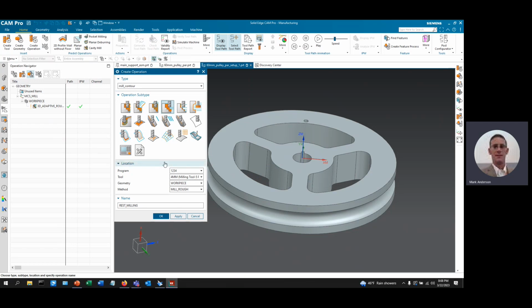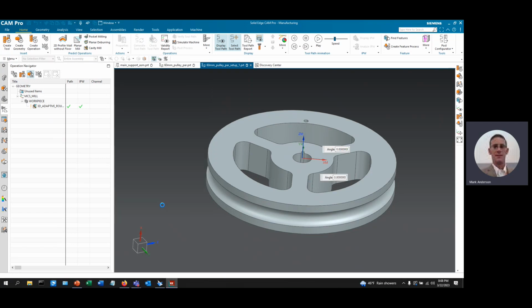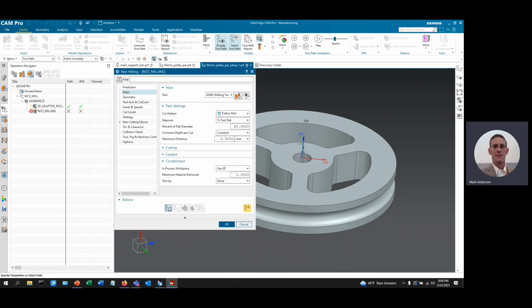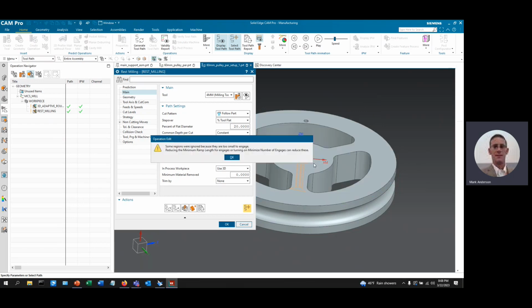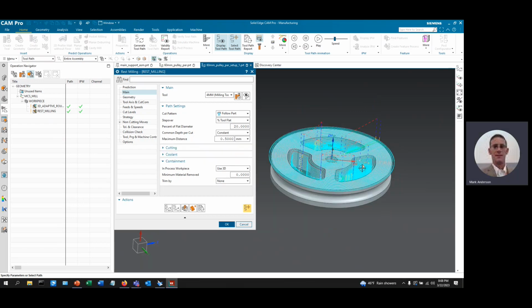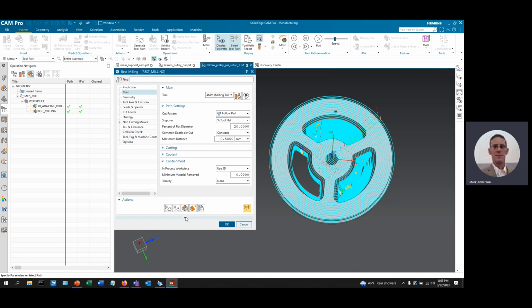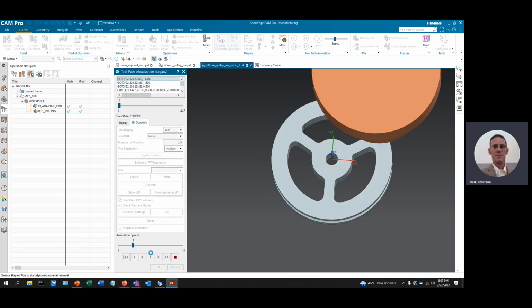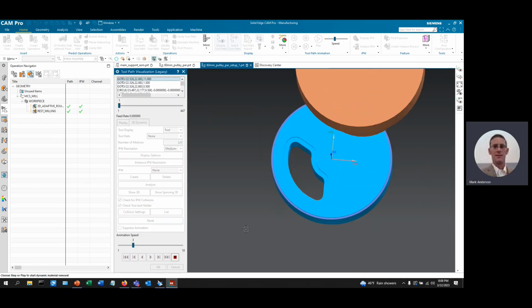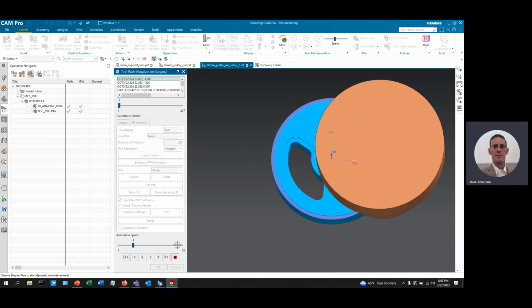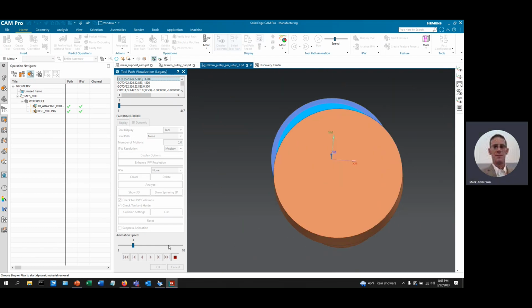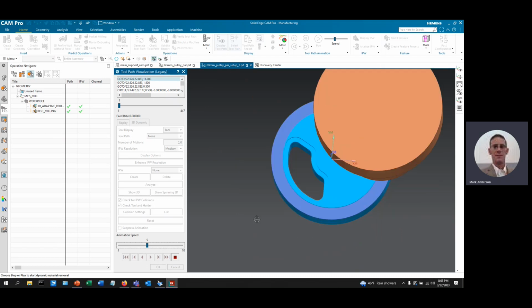This is to go directly after roughing strategies to cut the rest of the material. So if I just went ahead and left that tool alone and selected finish, you'll see that this operation is only going to cut material. It's not going to look at that as volumetric. There was material left on it, and these also had material left in the pockets. So you'll see that intelligently cut everything where there was material only. Very important that you see the differentiating factor between only where material is located.